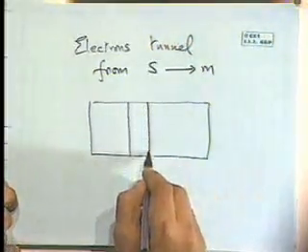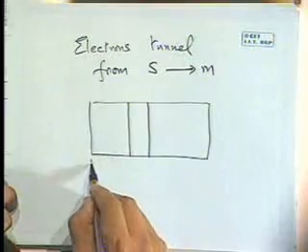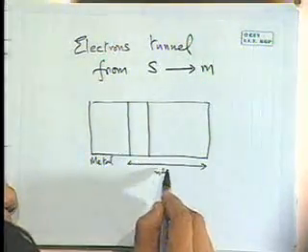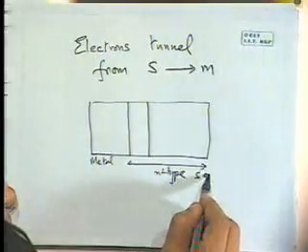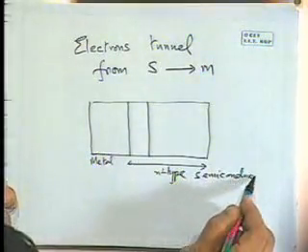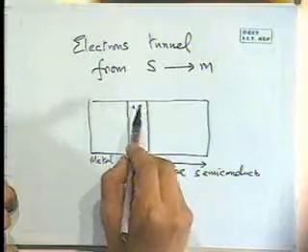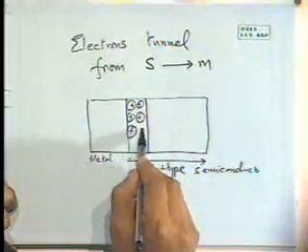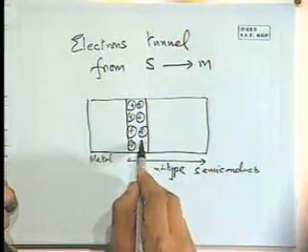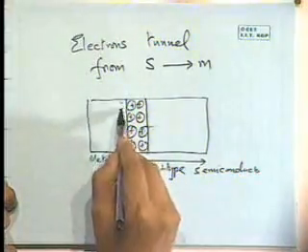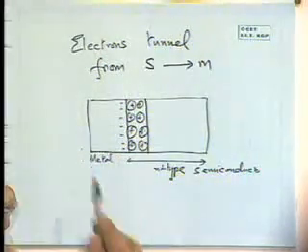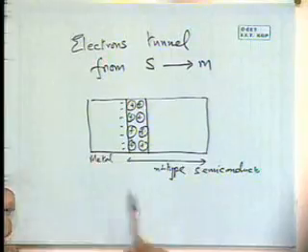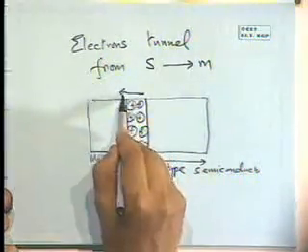There will be, in this interface here between the metal and the semiconductor, some region where there will be positive charges that are left behind. Okay? And then you have the accumulation of electrons as they have tunneled through from the semiconductor because of their higher energy. So a field is now set up in this direction,